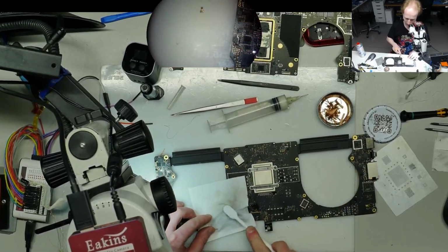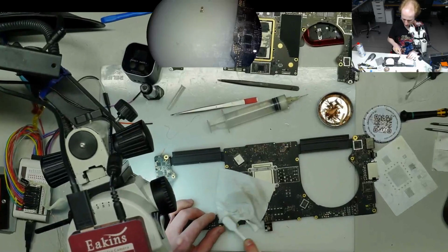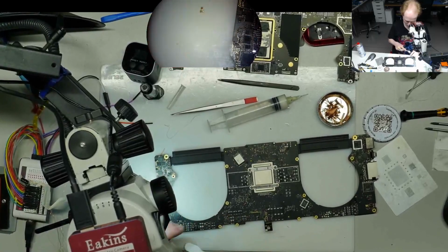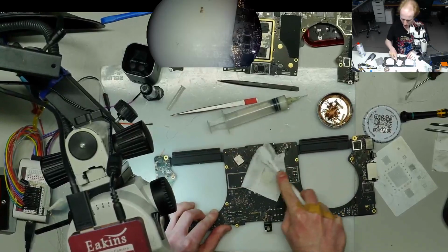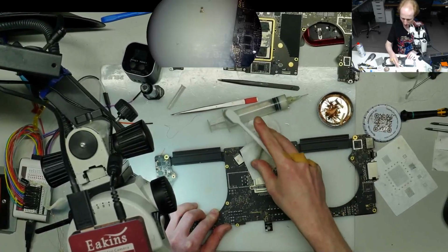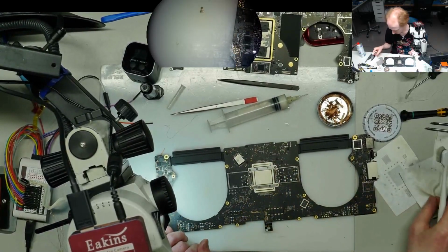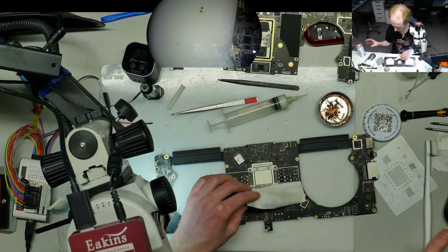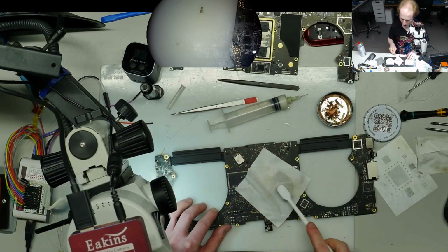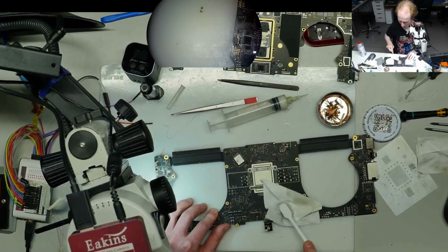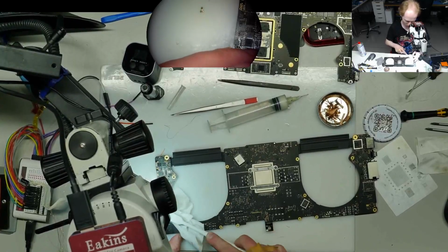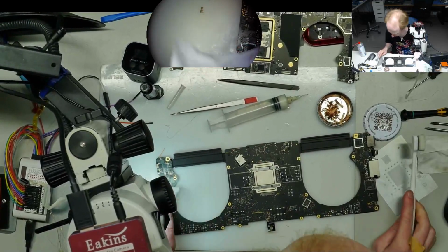So Apple is really conservative in some smaller chips. Which is both pro and con, because like using the very same SSD power IC which they used before, they use it now for 5-volt rail on the right side, and it fails, obviously, killing the right side USB-C port. Just a typical failure.